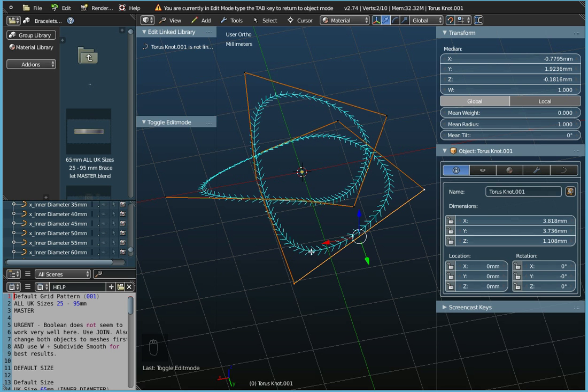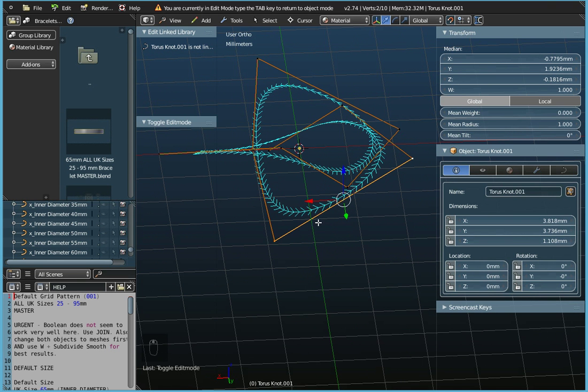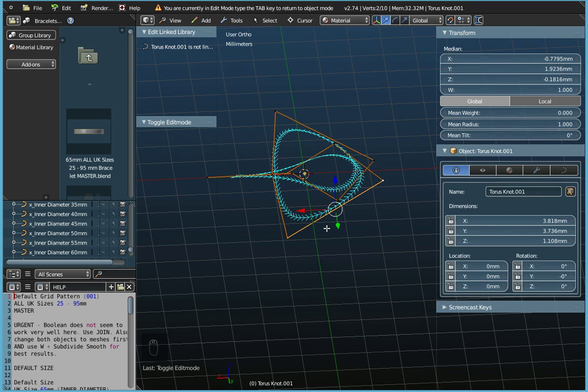And so the surface resolution increases the number of arrows between these 2 points. And what that does when we create a mesh out of our object is it increases the number of faces between those 2 control points. And clearly, the more faces you have, the smoother your object will become. So if we count these, we'd have 15 arrows here. So the more we have, the smoother our surface will be.